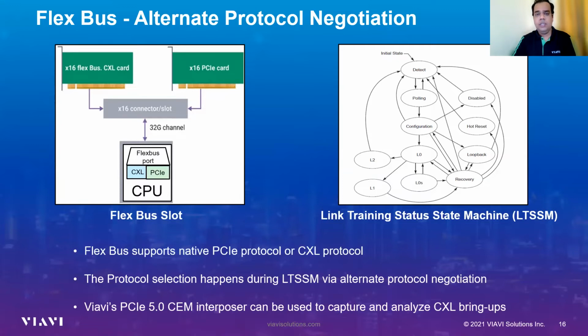Now, the selection of the protocol takes place during what is called the LTSSM process, shown on the right-hand side. Clearly, the LTSSM is defined in the PCIe specification. And when a PCIe card is plugged in, it goes through various phases or states of the LTSSM and gets into the L0 state and starts communicating in the PCIe protocol.